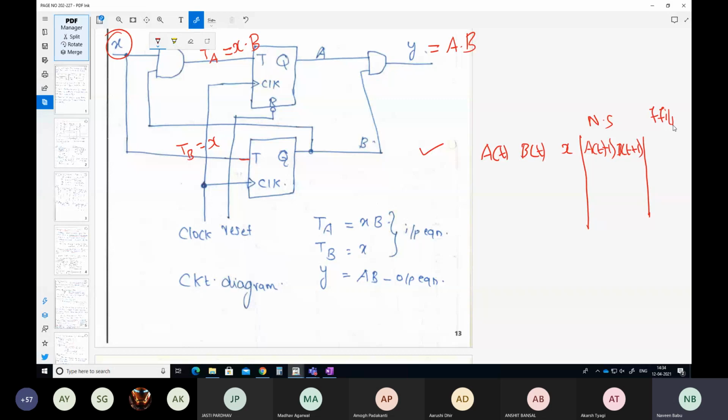And then your flip-flop input equations. In addition to that, I'm sorry, I don't have space here. You will have an output equation for Y also as a last column. So first thing is you will write all input combinations here, and then you will fill up the flip-flop input equations from these three equations, and you will fill up the output equation from the last equation here. Then based on your present state and your flip-flop input, you will fill up the next state equation using the characteristic table that we have derived for a T flip-flop. So this is the procedure.